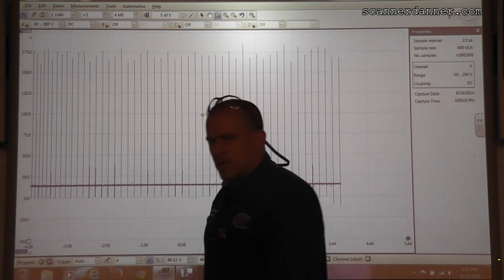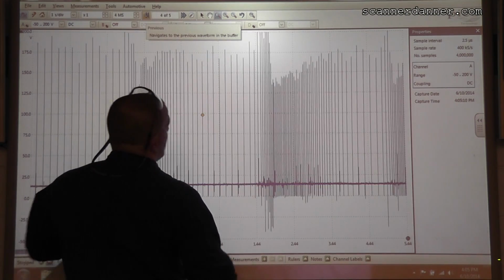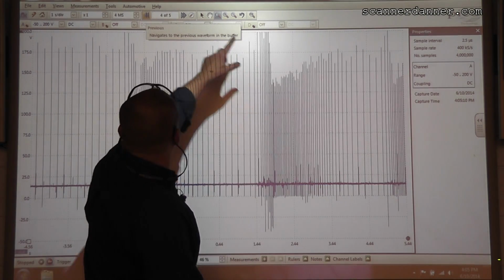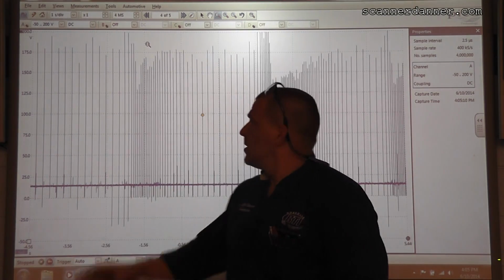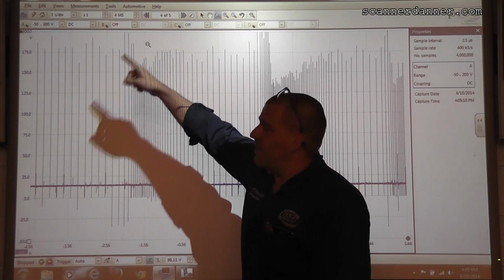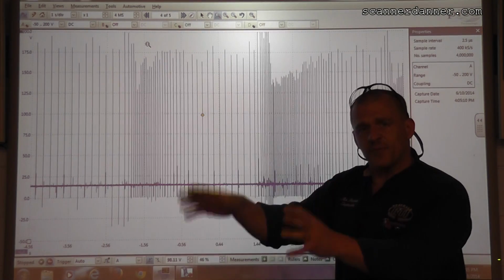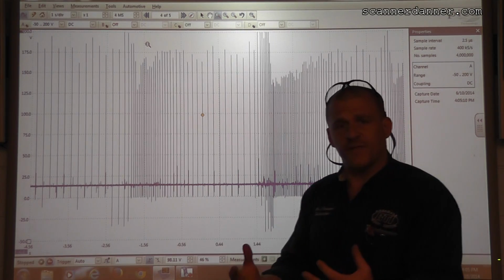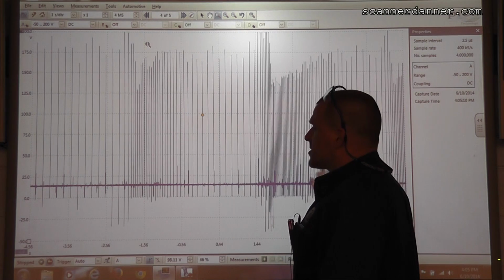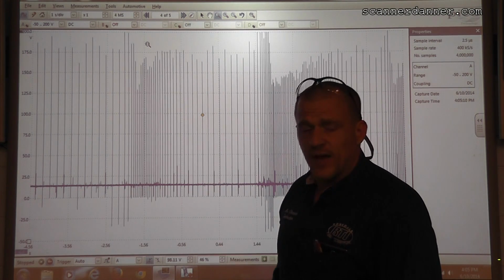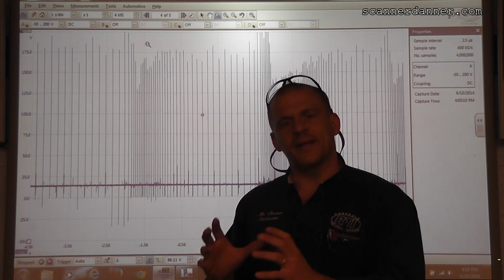Let's pause this, and we need to go back and look at where I snapped it. And maybe hypothetically, sorry, all I did was back up 1 frame. I'm on frame 4 now. And all I did was, hypothetically, I snapped the throttle, and maybe we have a misfire that we're trying to catch. And that would be when maybe we'd want to set this long of a time base looking at an ignition event. I have an ignition misfire that occurs on a snap, and I'm trying to catch it.